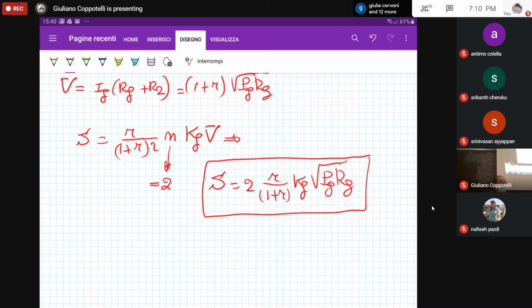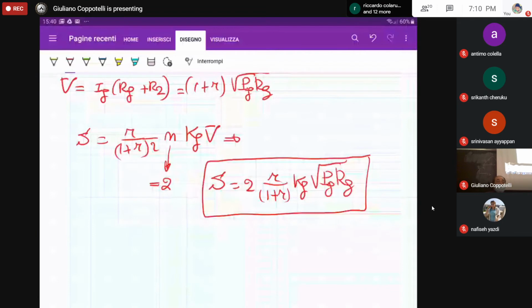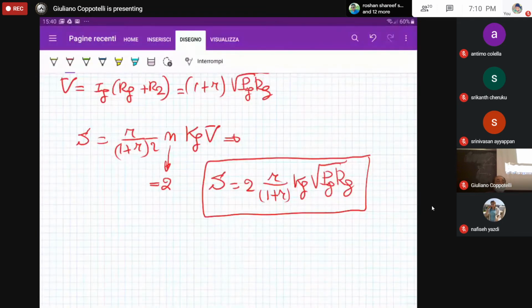Only for very specific points, where we want to be more than 100% sure of the results and have very high sensitivity in the measurement, do we use the full bridge configuration. So the pro is high sensitivity with the full bridge configuration.